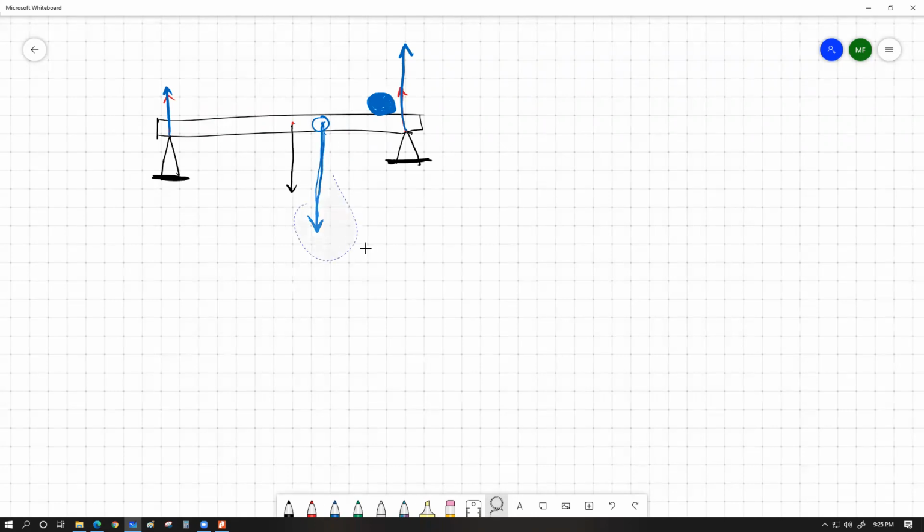Can I use loop while overlapping objects? I can. Beautiful. In this case, the entire center of gravity would be moving more to the right, and that is going to cause a significant increase in the reaction force on this side, and this reaction force is going to drop a little bit than earlier, but still going to be bigger than the exclusive weight of the single plank.